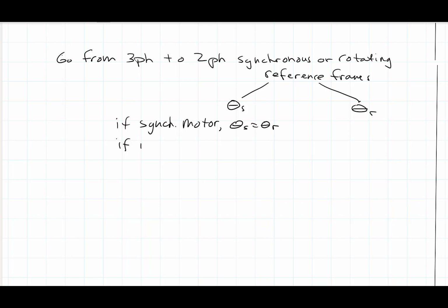If it's an induction motor, theta s does not equal theta r because of the slip, so there's a slight difference. In induction motors, you often want to use the rotating reference frame, the rotor reference frame.